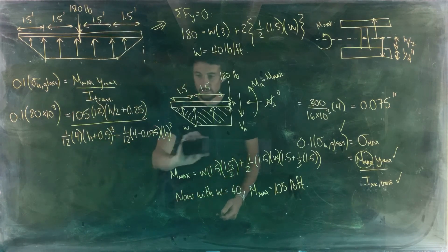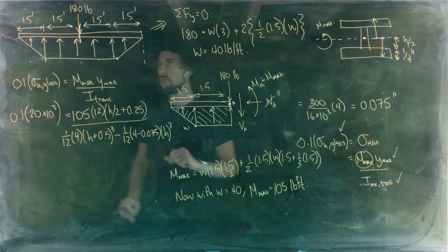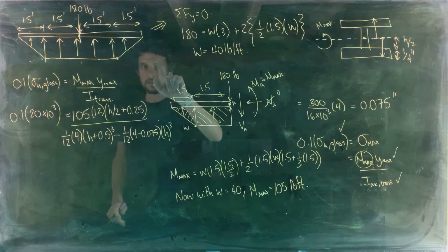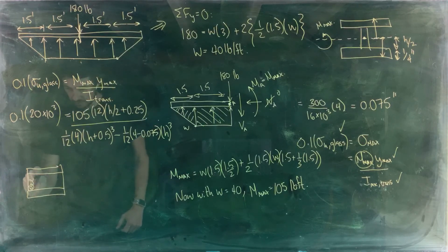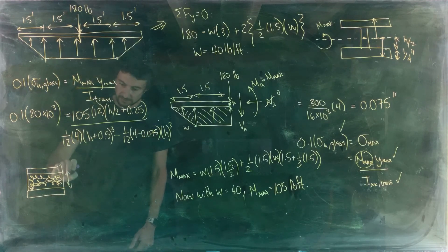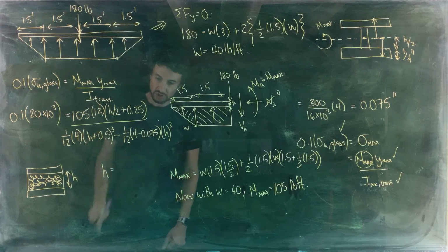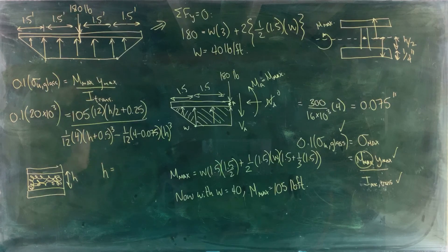All right, great. So solve for h, and you get the required height of the foam in the middle of the sandwich for that ski, right? That would be required so that under the loading situation shown, we'd only be at 10% of the fracture stress for the fiberglass. So there's H. So H equals, when I put this into my calculator and asked it to solve the equation for me, it gave me 0.549.